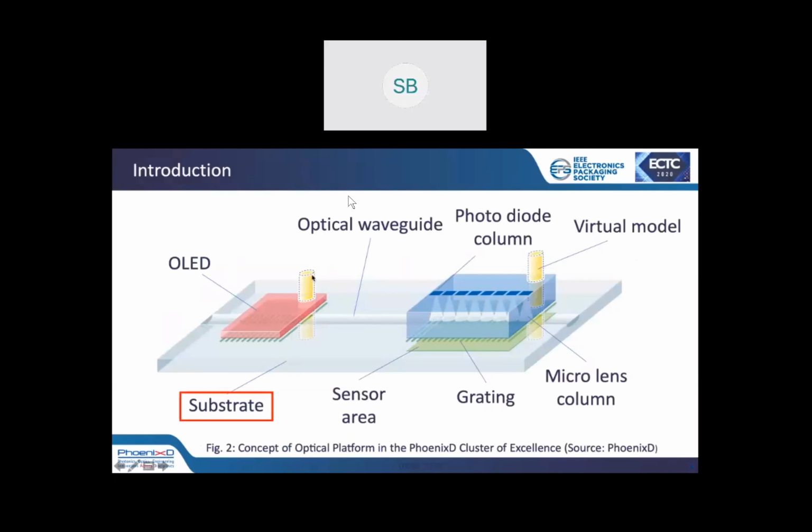This polymer platform was based on the laser direct structurable polyether-ether ketone and could be manufactured using the injection molding techniques. We created surface roughness on the electroplated structures on the steels, on different steel substrates, stainless steel or low alloy steel, for the waveguide channels.